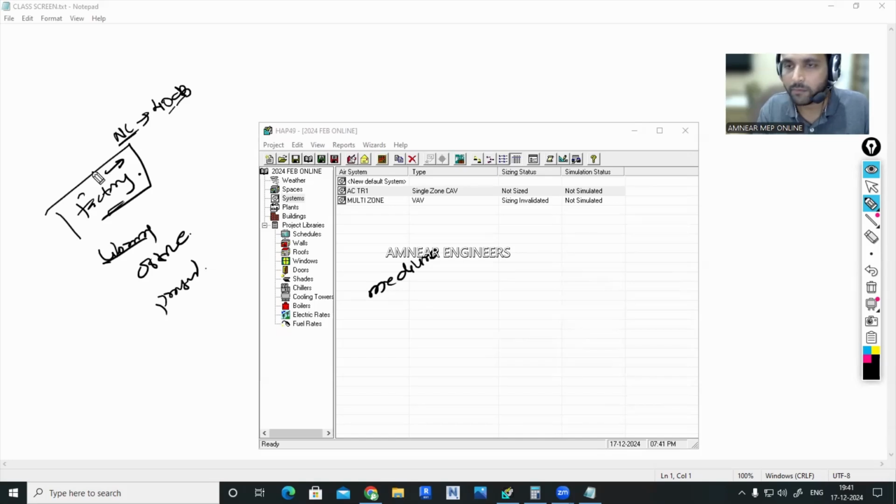But energy consumption will be very high, because in a high speed machine the blower motor RPM will be very high. That's why power consumption will be slightly high there. Noise issues can also come. But if the noise created by the machine, even when working at high speed, is within the limit of the NC value, no problem. You can propose that.